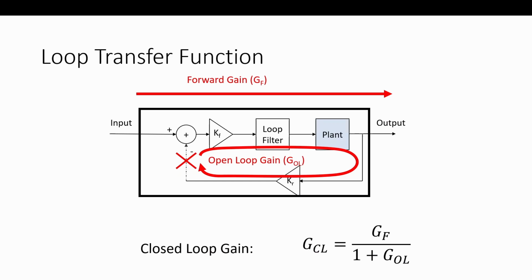So any system that I would put inside the loop, I want it to be 10 times higher in frequency than the loop bandwidth, and now it's only affecting it very slightly. The 100x will have no effect at all. But if you start competing with it, now it's part of your loop, and you have to consider it, especially if I have a high order loop.